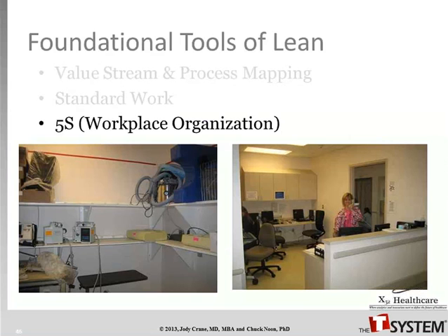The next tool is called 5S, and that's just an approach to workplace organization. I tend to think of it as cleaning out your attic or your garage, but doing it in a really systematized way. So it's sort, simplify, sweep, standardize, sustain.